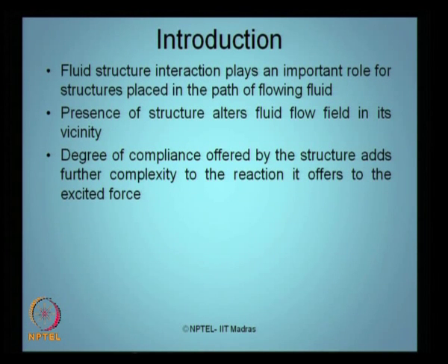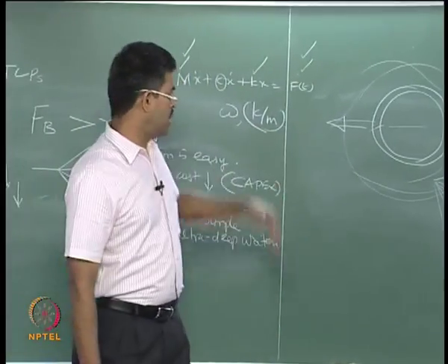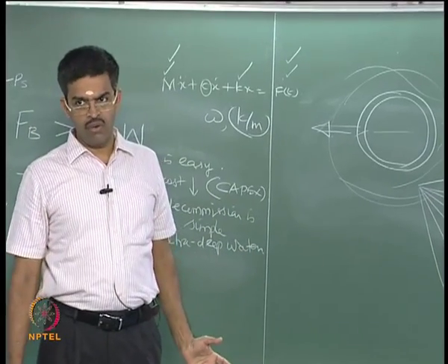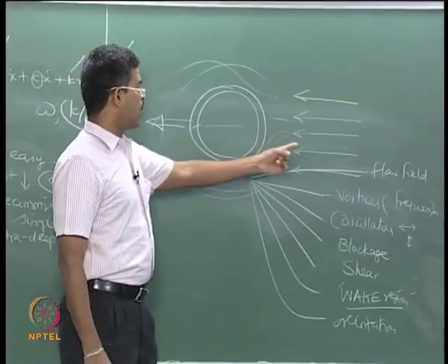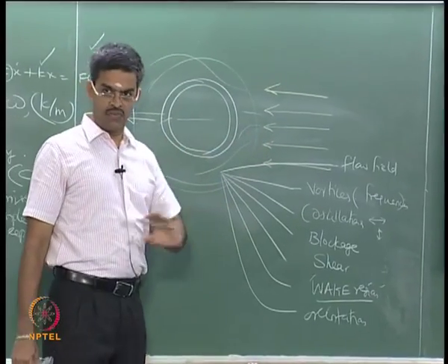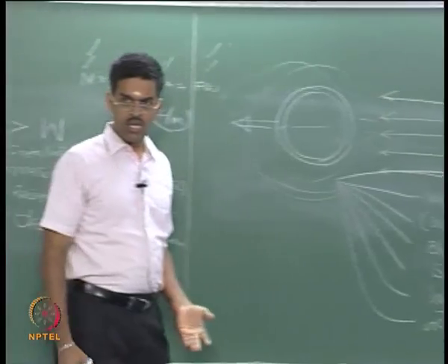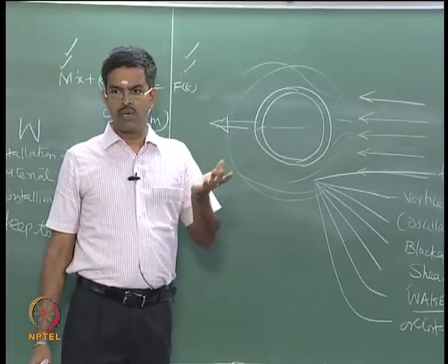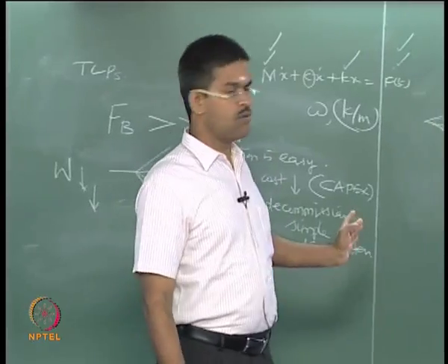For example, if the member is fixed to the bottom, if the member is infinitely long, if the boundary conditions have no effect on the fluid flow, then the behavior of the member is different, or the interference of fluid on the structure in the vicinity is different. If the member has a finite length with the member's ends closed and the member is closer to the submerged region or closer to the free surface, then the boundary effects will play a role on this.